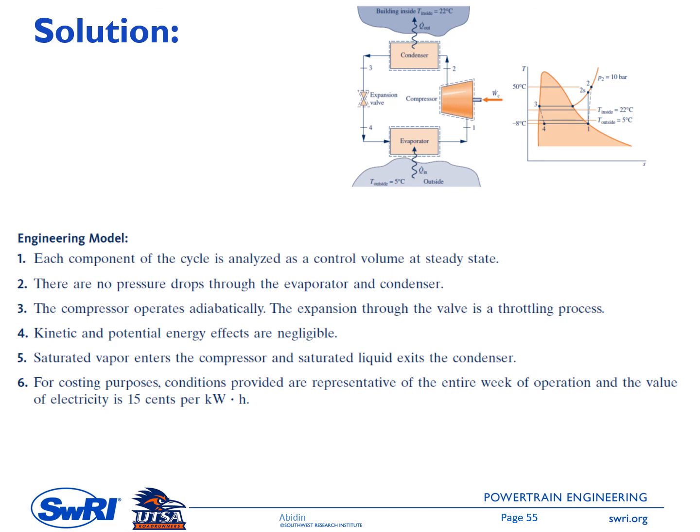This is the schematic of the system. We have a compressor, and then condenser, evaporator, and then expansion valve. And then the right side is the T-S diagram. So point 1 is at the entrance of the compressor, and it's supposed there is internal irreversibility inside the compressor. Therefore, we have a dashed line connecting state 1 to state 2 here.